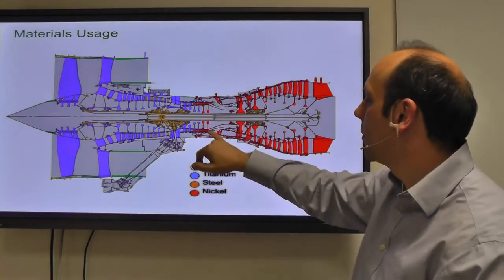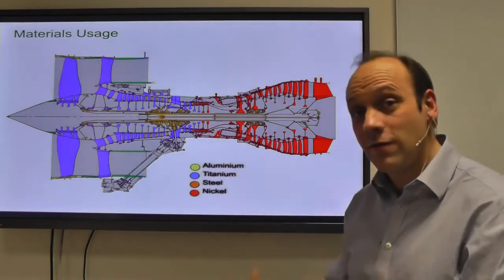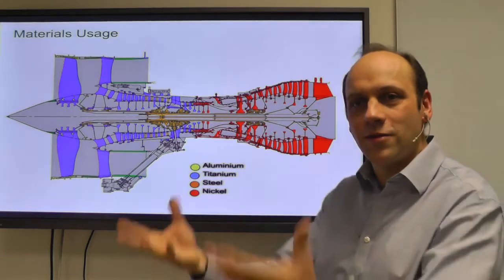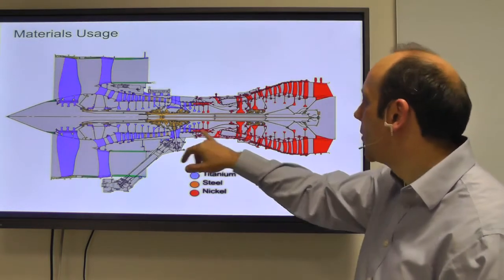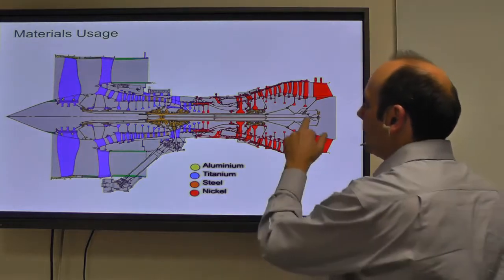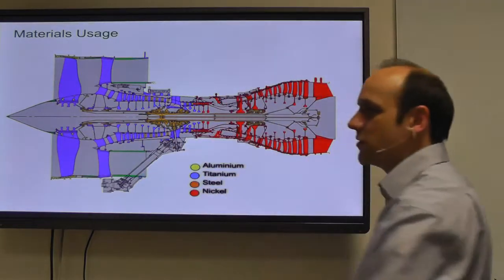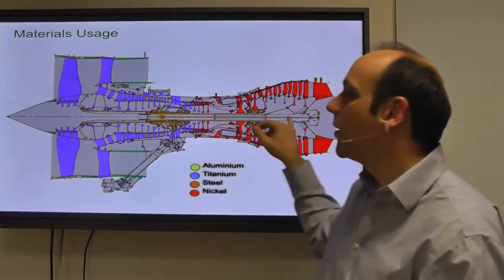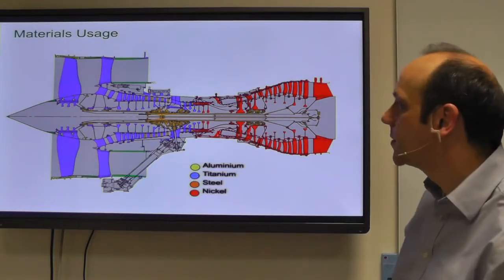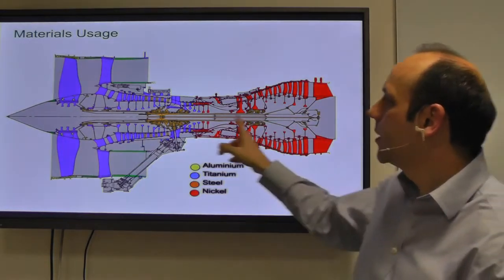And then that's when you start to need the creep resistance of nickel superalloys and the very good high temperature strength, given by the remarkable properties of nickel superalloys. And then you're all nickel out the back here. Down through here, your shaft temperatures are probably a mere couple of 100 degrees, and there you're using very high strength VAR steels, things like Jethete, which is making up the shafts.